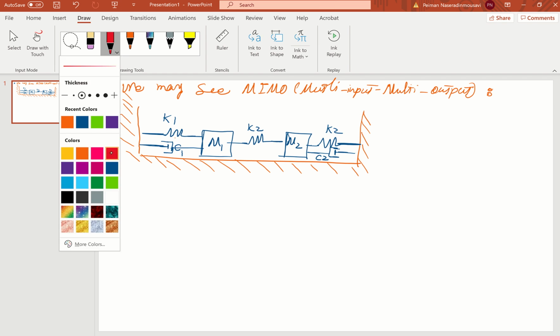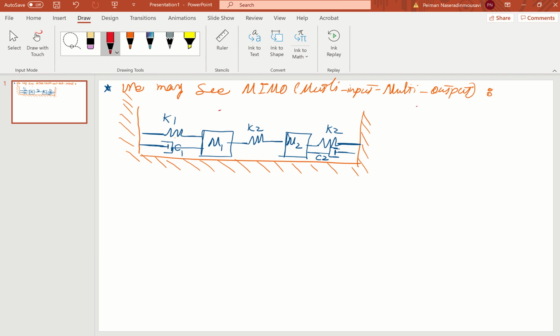Obviously this system has how many degrees of freedom? 2 degrees of freedom, because you have 2 displacements that are independent from each other, x1 and x2. But your boss says, okay, you have this mass, spring and damper system, you design a controller u1 and u2, for example, so that x1 at time infinity goes to r1.